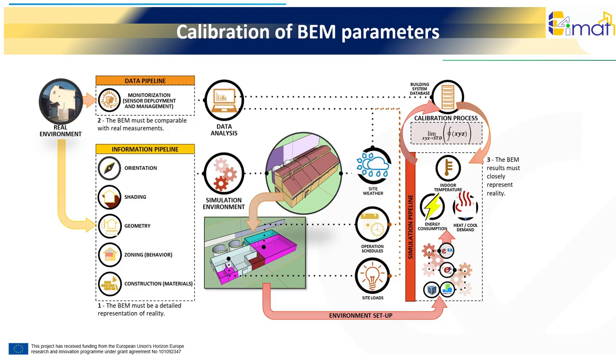Today's BEM development combines physics-based modeling with data-driven insights from a variety of sensors, IoT platforms, and management systems to increase the robustness of the model. The current training course delves into graybox models that can couple thermal behavior, occupant shifts, and weather patterns with real-time data streams. Their development requires expertise, accurate and organized management of raw data, and careful attention to detail, especially as the model's complexity increases. Sometimes, even state-of-the-art BEMs can have trouble predicting real-world performance.